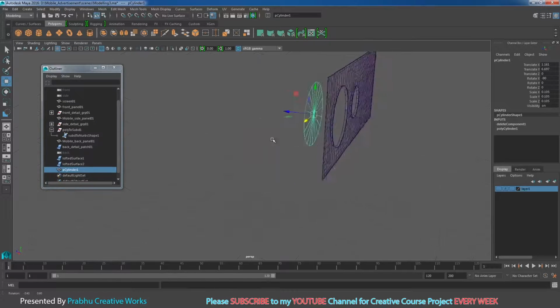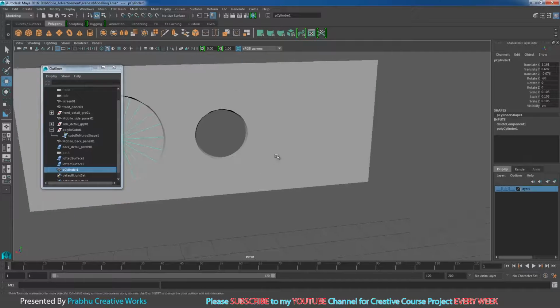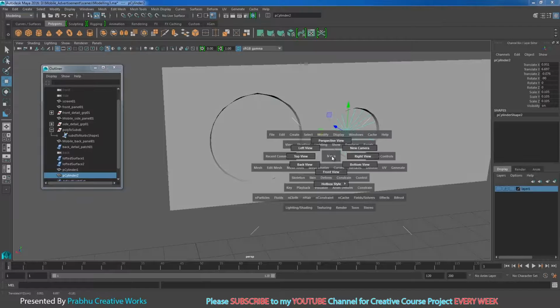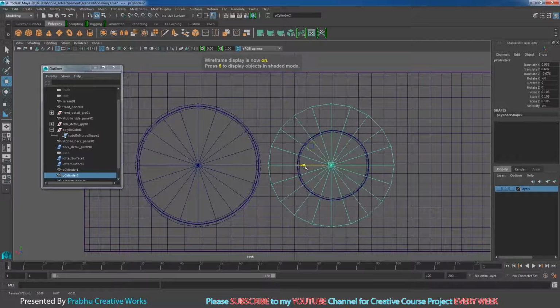So now I want to press 5 on the keyboard to see the shaded mode. You want to move this one in Z until it reaches that part. So now press Ctrl D and move it all the way to this side. So go to back view, press 4 on the keyboard to see the wireframe.